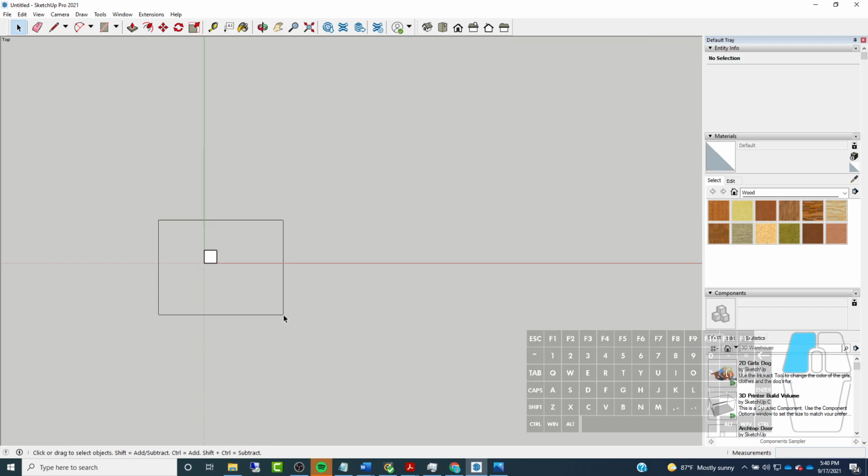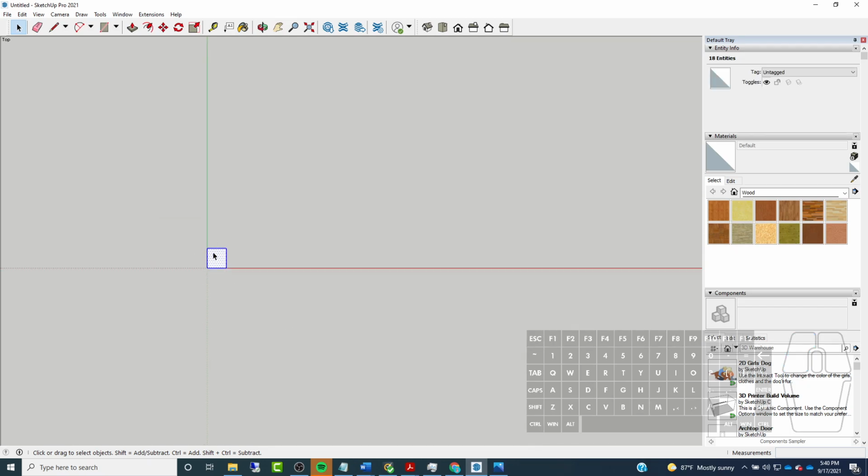Let's say I want to copy this cube, and I'm going to make this a group, by the way. It's always good to make things a group after you make them. I'm going to copy this cube to the right 5 times, and then I also want to do it up 5 times. And I want them to be spaced, I don't know, maybe 5 feet apart.